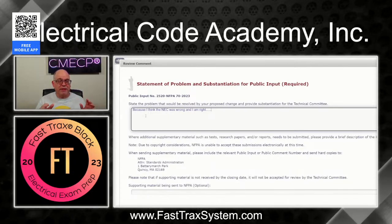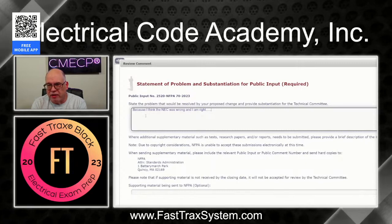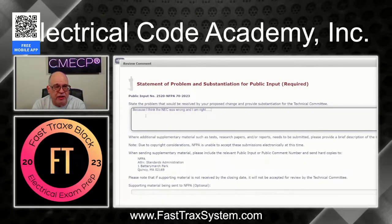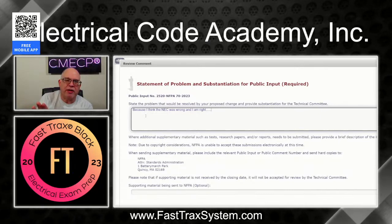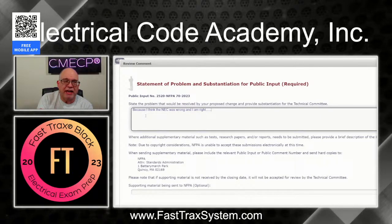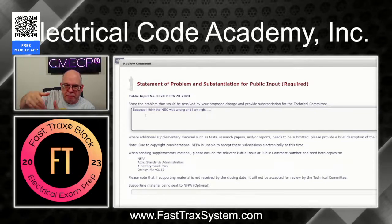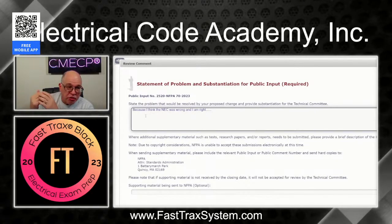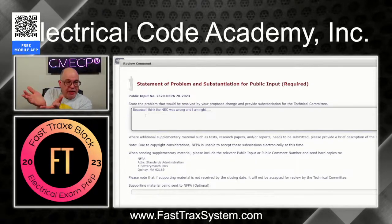That's not going to work. You need to substantiate it. Listen, all you folks out there who don't like certain things in the NEC, I'll use a great example. How many people out there think that 312.5(C), where you bring all those non-metallic sheathed cables through one connector in the back of an exterior enclosure, is okay? Well, here you go.